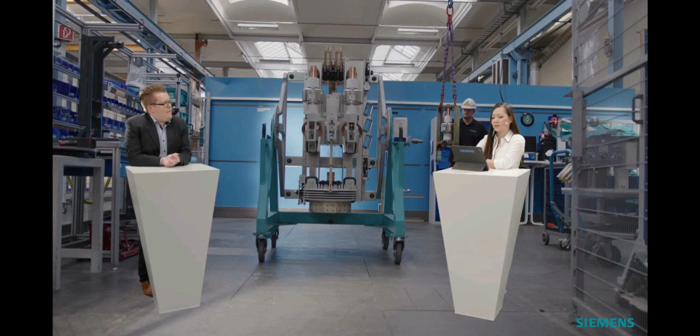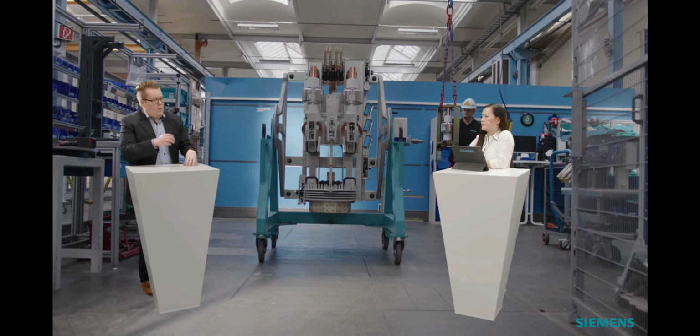All right. Another question regarding the calculation: how do you consider arc voltage in your simulation? The arc voltage is very important. The IEC/IEEE standard requires considering the arc voltage characteristic of each circuit breaker in our short circuit calculation. So when we have our contact opening, there is this arc voltage build-up, and we have to take it into account in our calculation. Of course, this is different from SF6, and that's why it is really important.